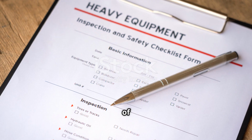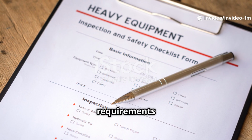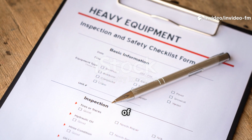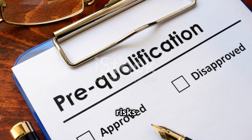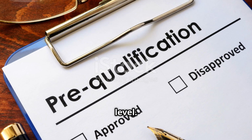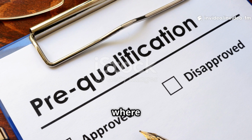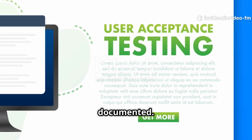The main stages of qualification are the following. 1. User requirement specifications, URS. The essential elements of quality need to be built in at this stage, and any GMP risks mitigated to an acceptable level. 2. Design qualification, DQ, where the compliance of the design with GMP should be demonstrated and documented.